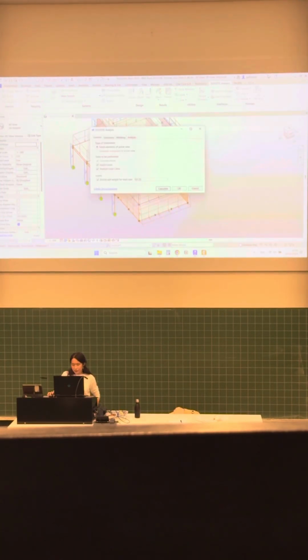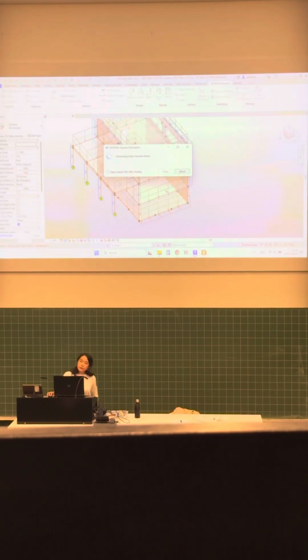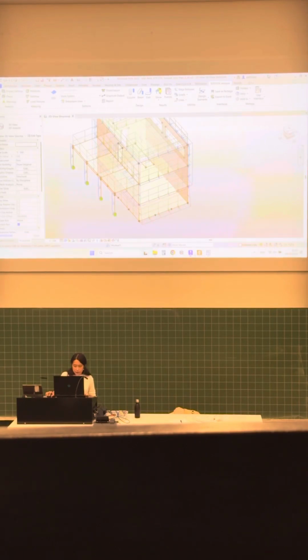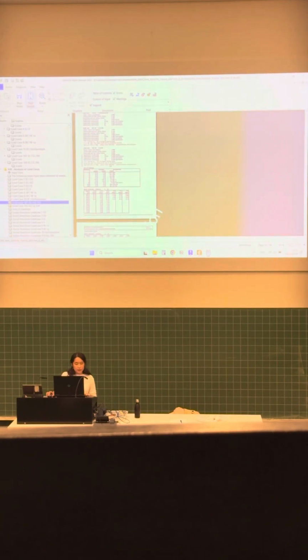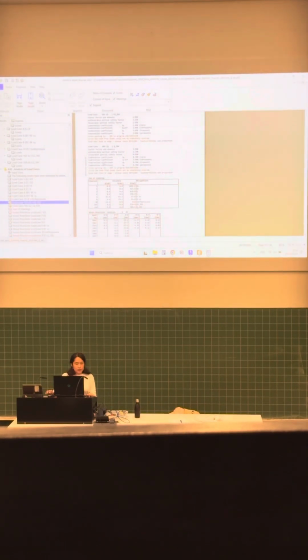So let's check it. Again, I did not click it. Close it. And we go back and we find the problem here. Yes, we have a similar problem. So changing the boundary did not work for us. We have to go back again, and maybe it's a problem with the loads on the balconies. So this is a trial and error time where you change it and go back.